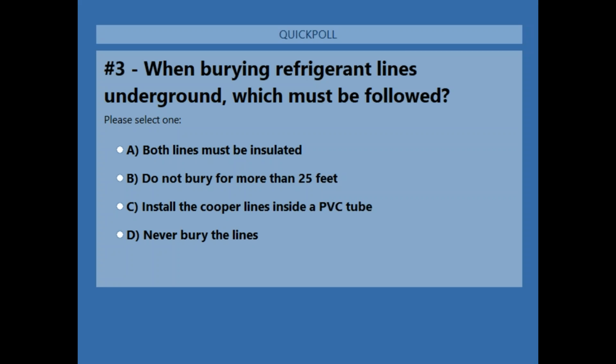One more question for Doug, though. This is from Chuck: what is the maximum length you can remote a package chiller evaporator? It's governed by the model number type of chiller. If you're looking at just the scrolls themselves, like your RAPs, RBs, those are right around 75 feet. You get into the XAs, the big screws, we can get a little bit more distance, not much more. But usually you're, let's say, 100 or under. Depends on the model.